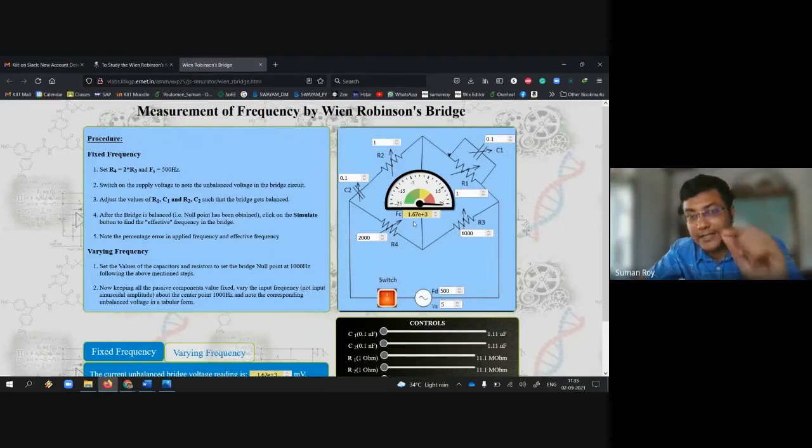Now, in this particular platform, there is, not a problem I would say, but the right procedure is like this. First, switch off the bridge, then only can you change this value from 1 to 2 or 200. Let's try with 200, but if you change it here, then you also have to change R2. Okay, and then switch it on. You can see nothing changed, so the value is still very high.